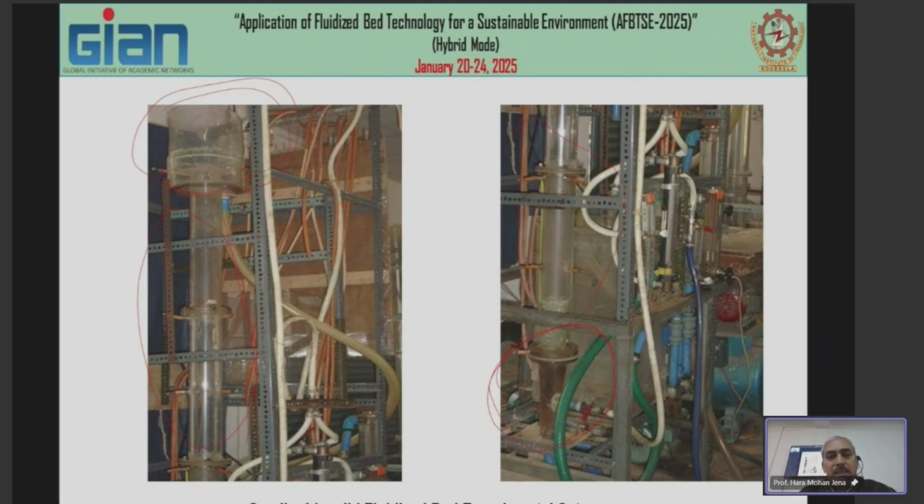The gas phase escapes to the atmosphere in this case, but it can also be collected and taken for some other processing. Similarly, the liquid is drained out and taken to the storage vessel, from where the liquid is pumped out. Again, it can be taken for other use for a continuous operation. This is a batch three-phase fluidized bed setup as far as the solid and the liquid are concerned. Liquid is circulating and the operation is continuous for the gas.